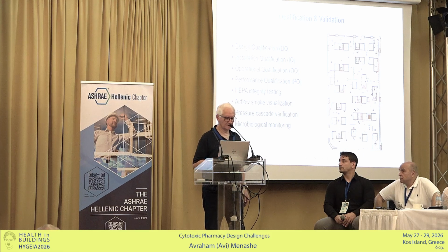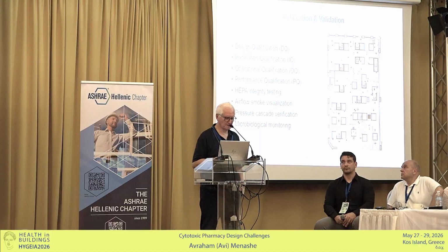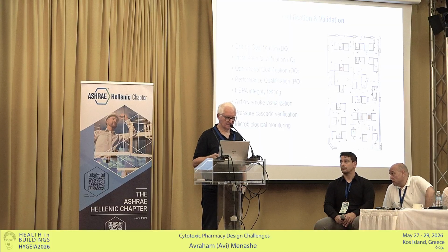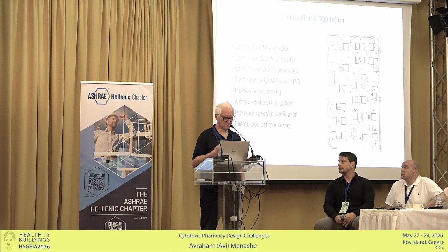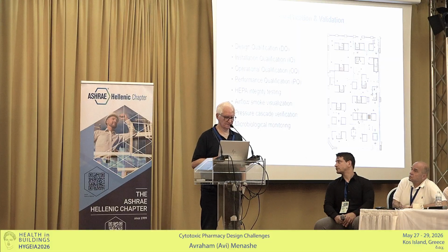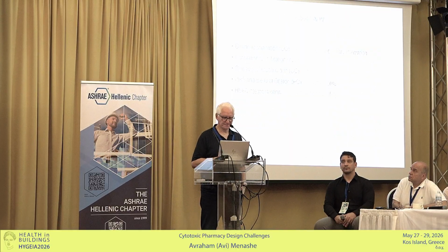We call it qualification and validation. So there is a set of testing: design qualification, DQ, IQ, OQ. I believe that if you're in this business, you know what it means. HEPA integrity testing is very important. Airflow smoke visualization: you're going to see that the air is going in a laminar flow. Pressure cascade, and biological monitoring.